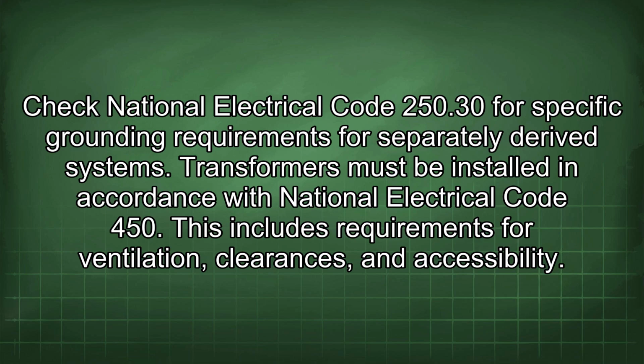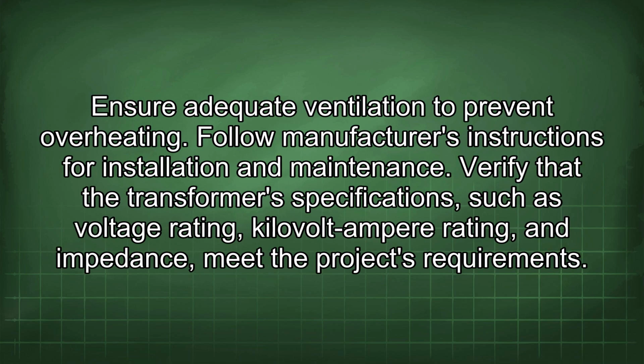Transformers must be installed in accordance with National Electrical Code 450. This includes requirements for ventilation, clearances, and accessibility. Ensure adequate ventilation to prevent overheating. Follow manufacturer's instructions for installation and maintenance.